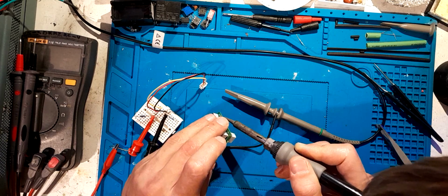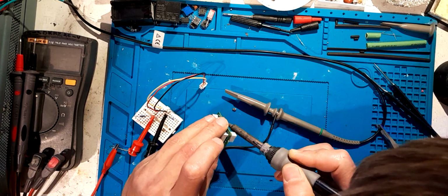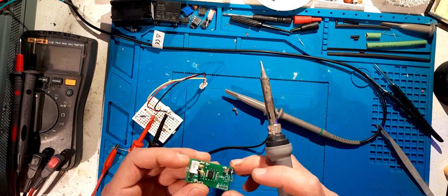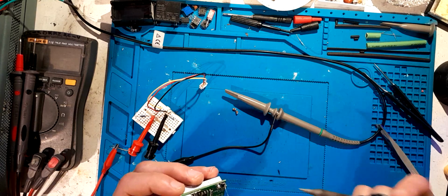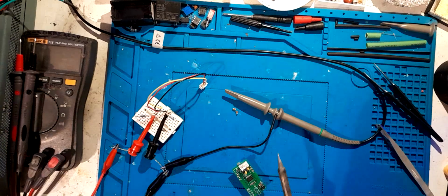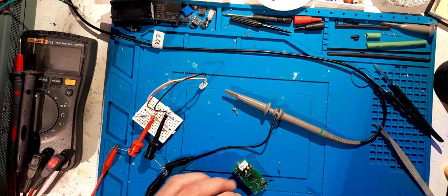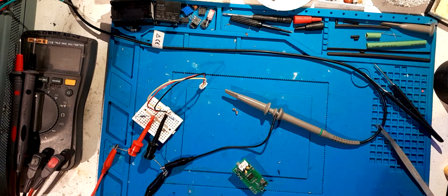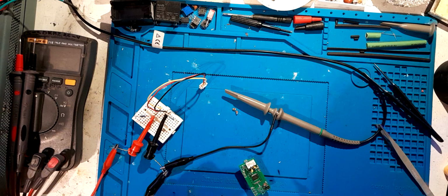I just want to see, we've only got 2 capacitors stacked up, what the ripple rejection's like, because if it really only needs about 20 microfarads, like just double 10, because I just want to point out, when I grabbed a 22 microfarad or a 10 microfarad cap and added it to it, it made the same difference these four did.